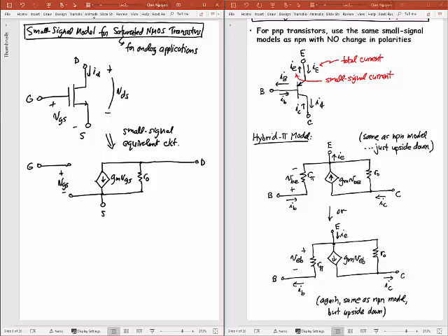And so we're going to do the same thing that we did to derive these small signal elements. I want to know what g_m is. I want to know what r_o is in this. And once I can get g_m and r_o, I have specified at least the small signal behavior of this transistor. And so let's go ahead and get these. Let me just say g_m is going to be a conductance again. So it's the conductance where I'm going to take my small signal i_d divided by my v_gs.